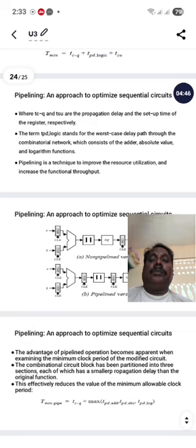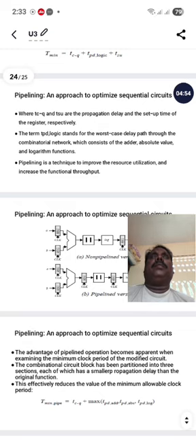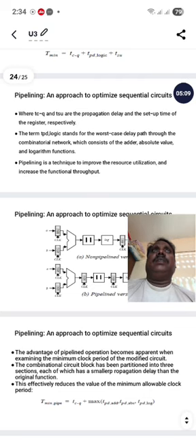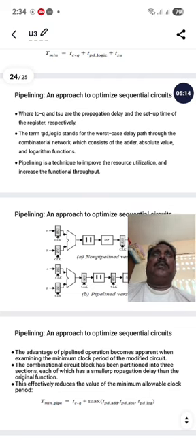But the most important thing is that we obtain the solution with respect to the propagation delay. If the propagation delay is more, the time taken for the operation is also more. To overcome this, I am moving to the concept called pipelining, in which the delay is very much less when compared with the other technique.